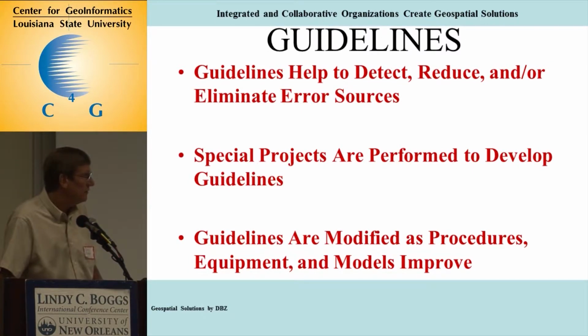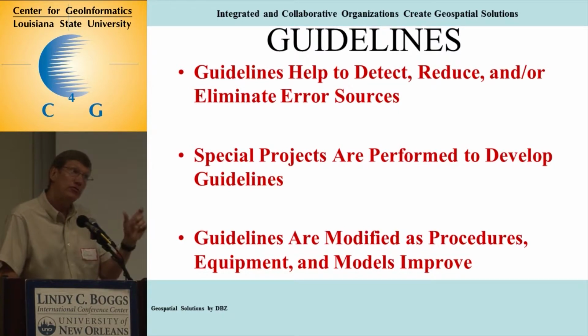Same thing with theodolites. If you remember when you took 16 positions, or if you did first order work, or you did 8 positions when you were coming down to go in the second, and you did it around a circle. All you were doing was eliminating the errors in the theodolite for around the circle. You had to take the mean. You did 16, and you got better if you did more. And as you got down to third order, maybe you did even less than that. But you still repeated it because you had to compensate. You had an error source that you had to eliminate by going around the circle.